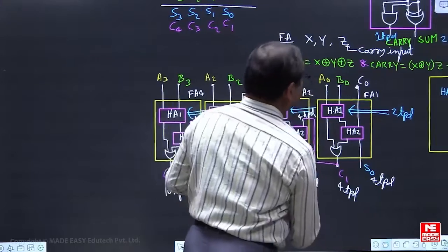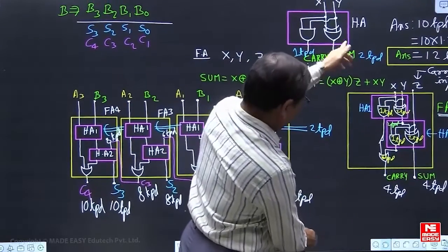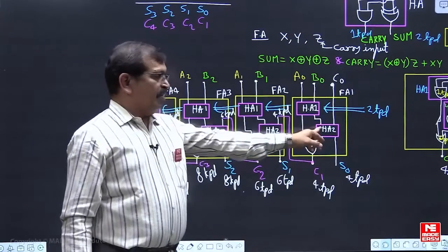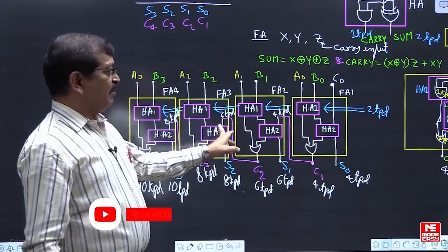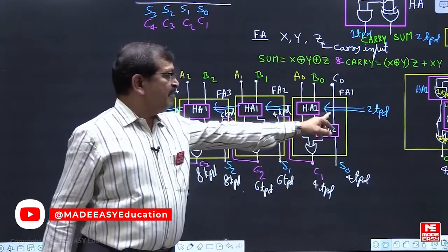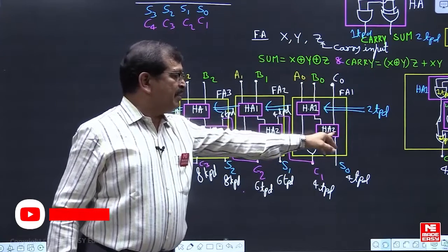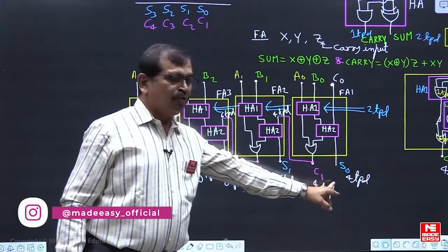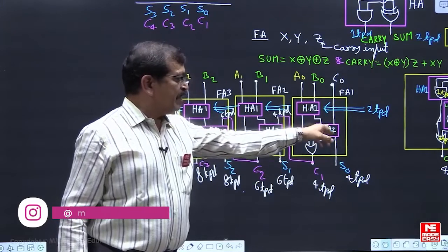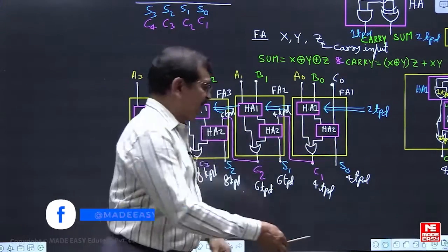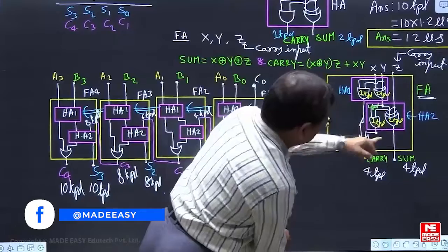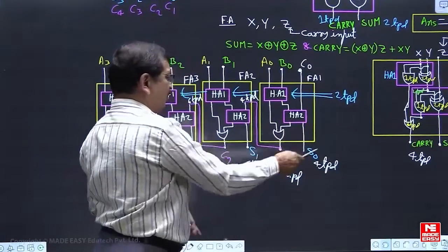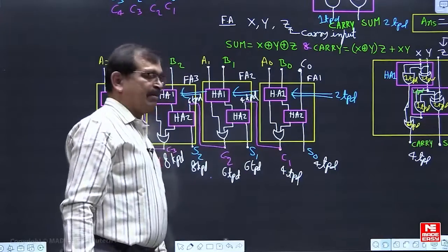We already took the explanation from this. Later, the half adder twos are looking for the carry input. For full adder 1, the carry is directly available, hence effectively sum and carry are available with 4 TPD delay, because after receiving it the half adder 2 has XOR, which is 2 TPD, and AND, so effectively 2 TPD is added, so 4 TPD for sum as well as carry.